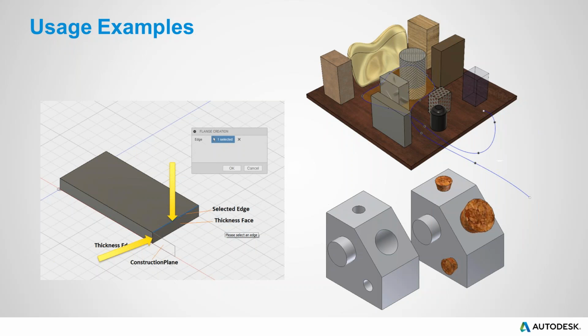Yeah, and so by getting the normal from the cylinder, I could figure out which edges I want. In this case, I got these 3 circular edges. From each edge, I can get the center of that edge and the normal of that plane. So now I have all the information I need to figure out the position of where that cork needs to go. I know the size because I have that circle, and I have the center point and a normal along that, and that's enough to figure out where the cork needs to go.